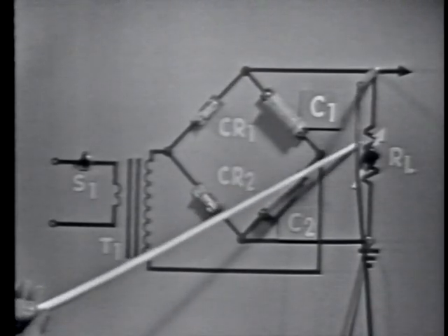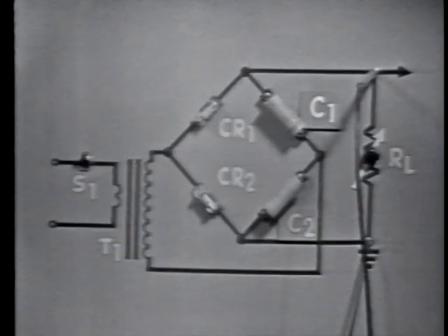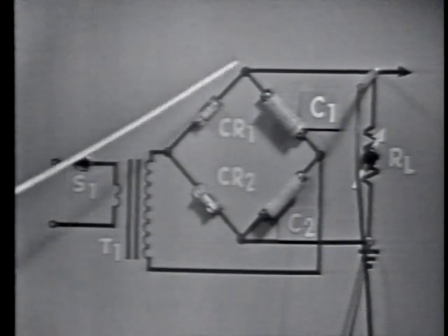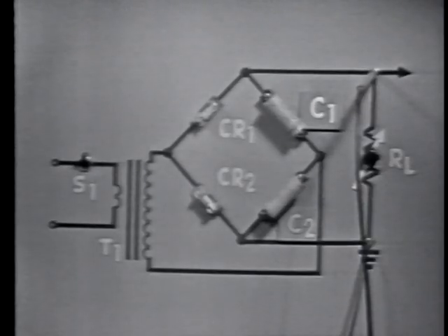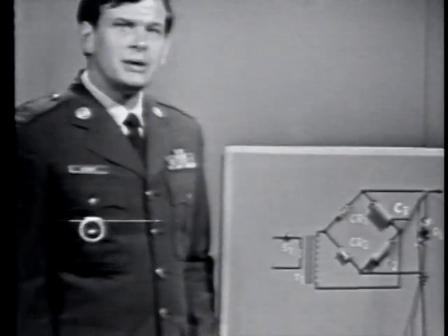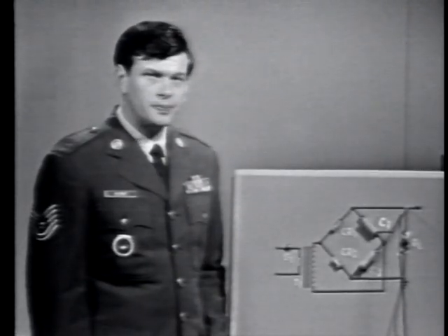With a long time constant, where the resistance is high, average output voltage is high. If the load on the circuit increases, resistance decreases, and this decrease in resistance shortens the time for one time constant. This then allows the capacitors, that's C1 and C2 in this circuit, to discharge a greater amount between cycles of the input. So, average output voltage decreases. By isolating a portion of the circuit, namely C1, C2, and the load, we've been able to analyze several important facts pertaining to voltage doubler operation.